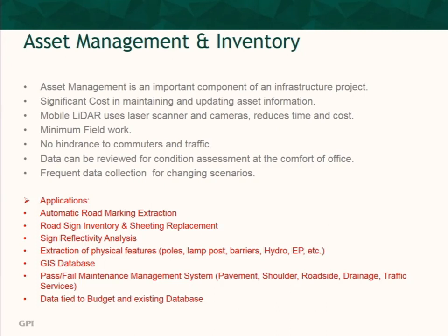And of course, all of this data is now placed into a database, and then you can imagine, all of the highway assets that they own, all in a nice compact database. And of course, pass and fail maintenance management systems. Some DOTs will go and collect video, georeference video, all of the roadways, and then decide on what to maintain and when, and prioritize depending on the assets that they have.